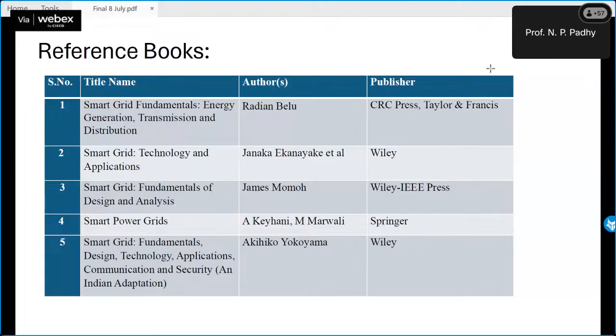Am I right? Only if the discharge cycle is during peak hours and the reverse water pumping is during off-peak hours, then the cheaper energy will be used to take the water back and generate during the costly hours. That is the philosophy. That's all.